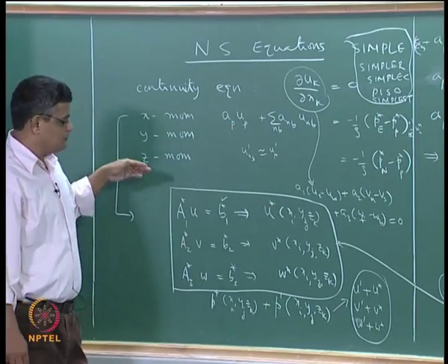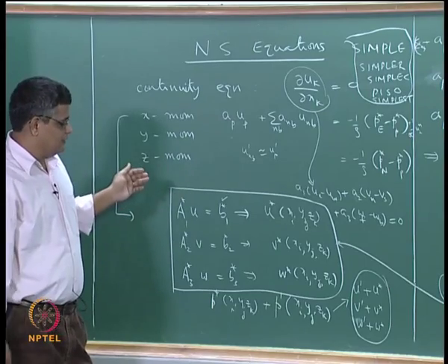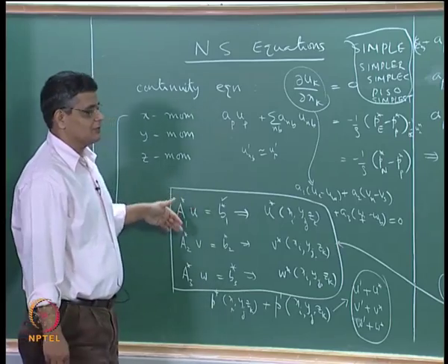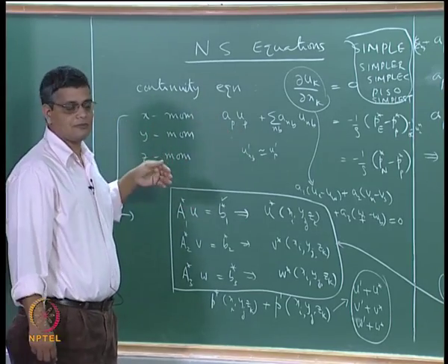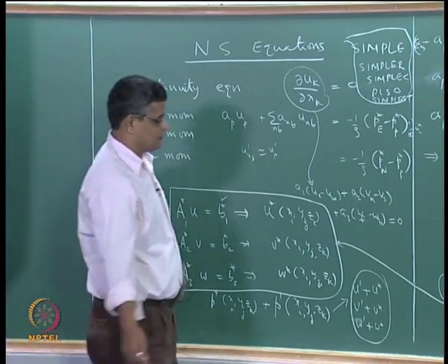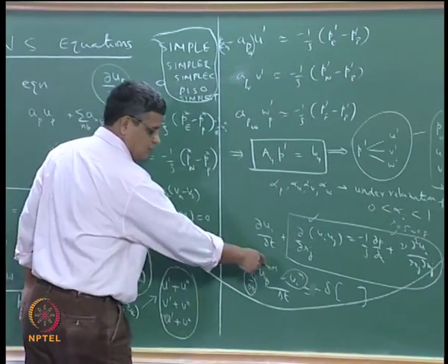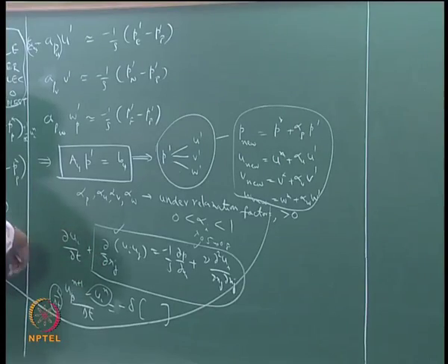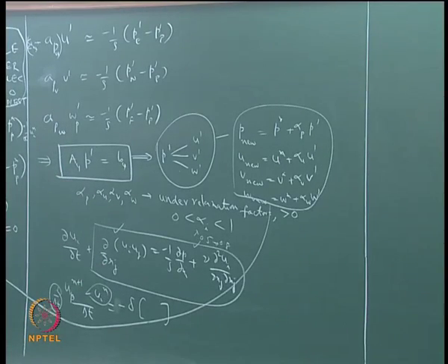So in this way we have a modification to the coefficients here, but otherwise the solution method will be the same, and if we follow the solution method, then ultimately the velocities that we get will be the velocities at the new time step. Then with those we have to come back to the discretized form and go from n plus 1 to n plus 2 and n plus 2 to n plus 3 and so on until we stop the calculation.